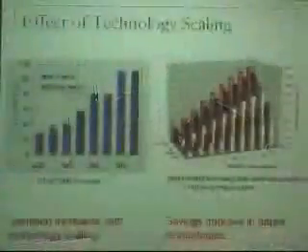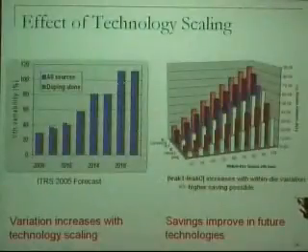And as you see here, these are the forecasts of ITRS. They said that we would have over 100% variation in VTH, but this is certainly not a thing that is going to happen, because if you have such a thing, then that SRAM cell would not really work. But to have just some forecast of the trend on how much leakage you can get, we just use these values. Yes, reliability is very important. And some people even say that the SRAM cells especially may not be shrunk anymore. But it is still to be seen.